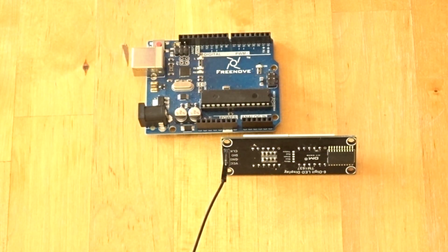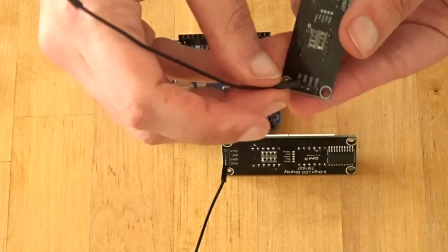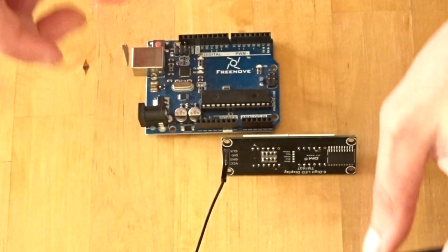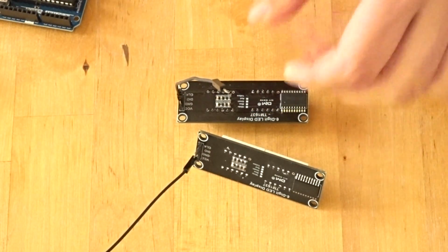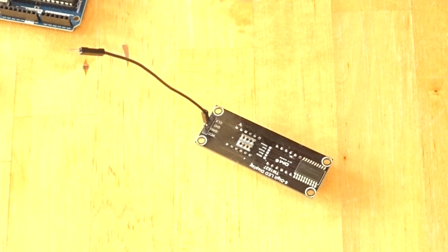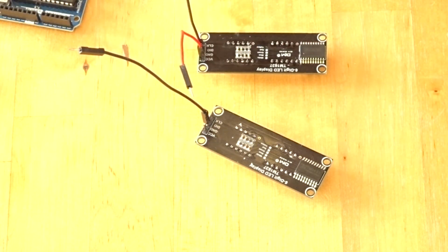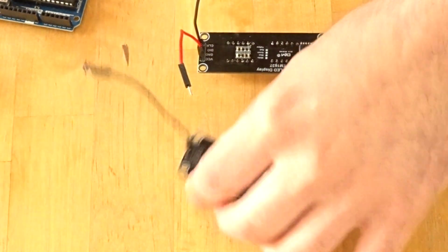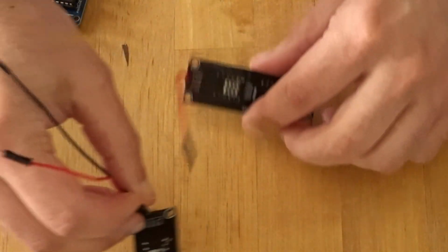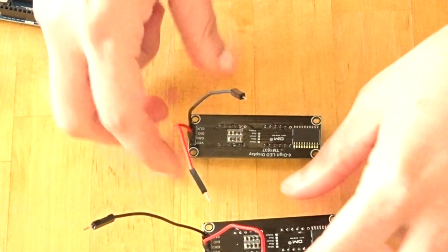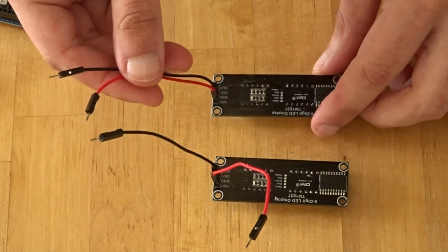Now you don't have to color code the wires, but I think it will make sure that you don't short anything if you can visually spot which is the ground and which is the 5 volts by just judging it based on color. So all the other wires aren't really that important to color code. Perhaps it's easy to match the diode with the same color on the diode so you know which wire is which. But for the ground and power, I always recommend to go with a designated red and black or brownish.